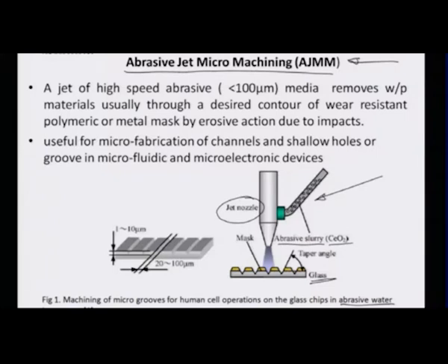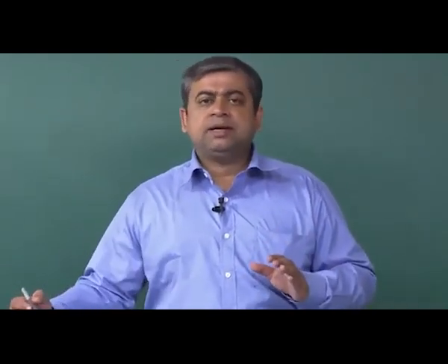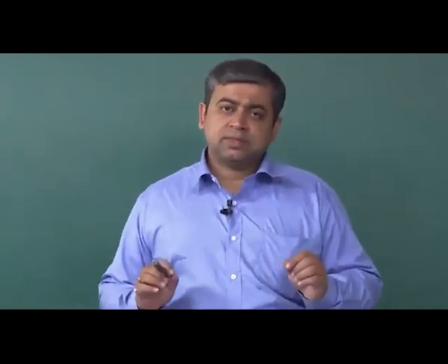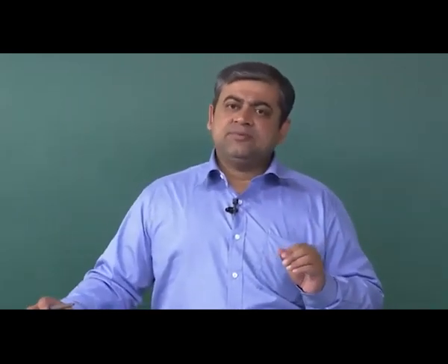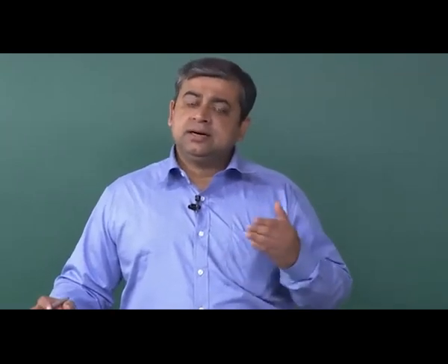So in all these processes where mechanical energy is introduced, creating a brittle fracture, as you go from the conventional macro size domain to the micro domain, one has to remember that the small tiny shapes and features which are to be incorporated on these substrate surfaces by virtue of the impact of the jet have to be a guided impact, and this guided impact can come from a mask, a secondary layer of a sacrificial material which has those features and structures, negative of them, embedded onto the surface, and where through holes are made by virtue of the negative of the features.